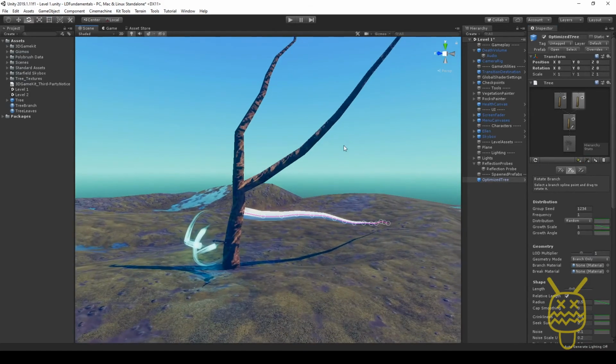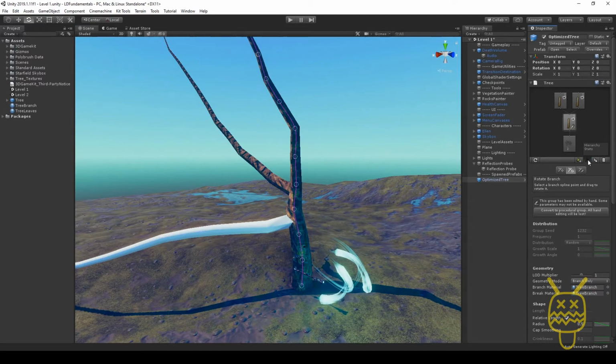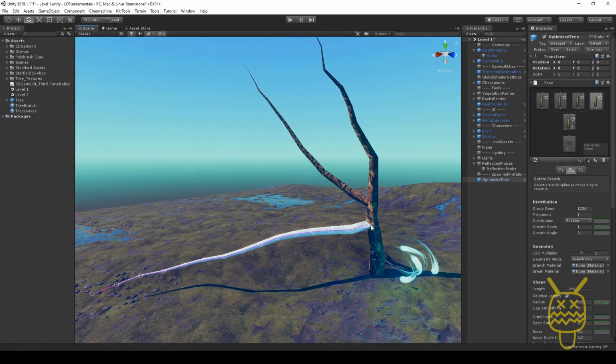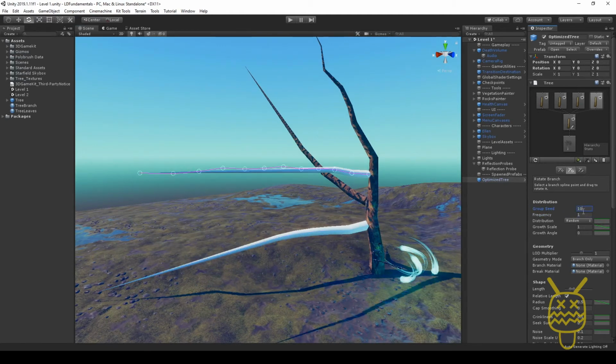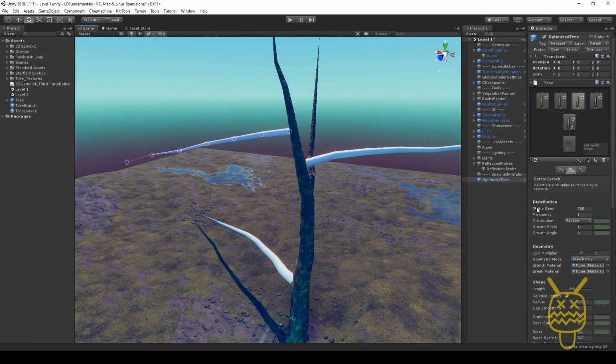It's going to add another branch directly onto the same tree. So now we get a branch that splits right here. You can do that multiple times. So if I do this again, and say for instance I do it again, now I've got four. Notice I only see these, but it's because all of them are seeded to the same spot. So if I go and select this one and we seed a different spot, so say we seed it to over here. There we go. And then we'll do another one with a change on it. So now we have different ones going different places.